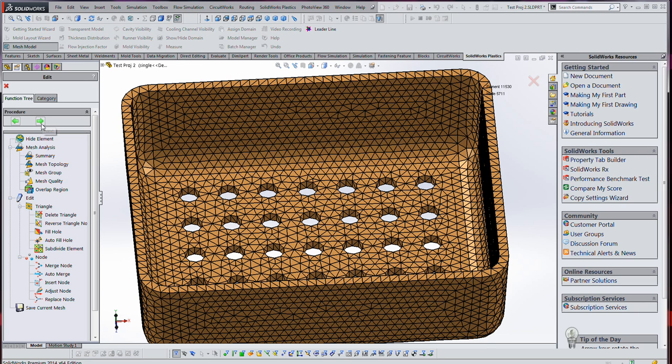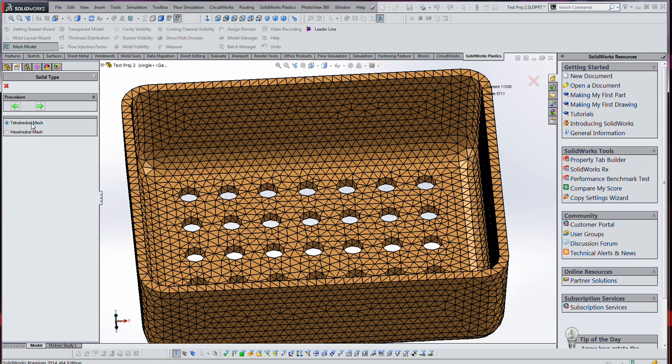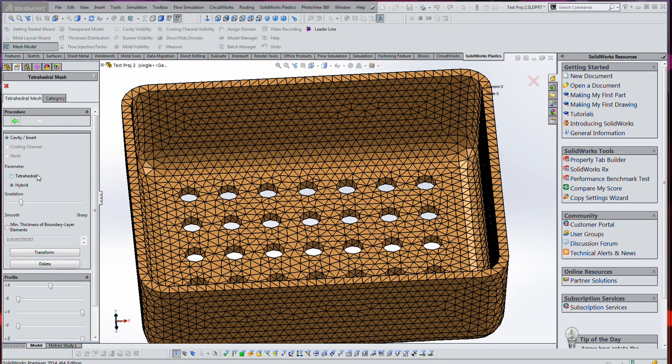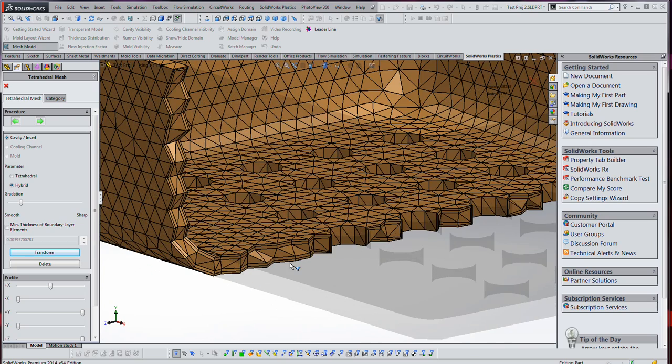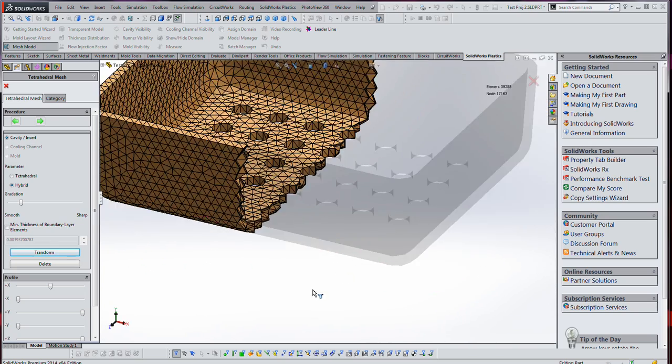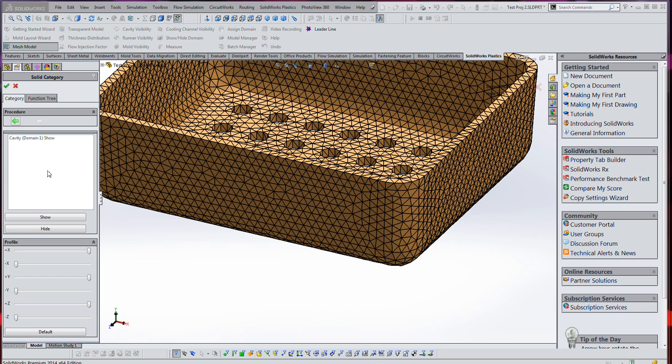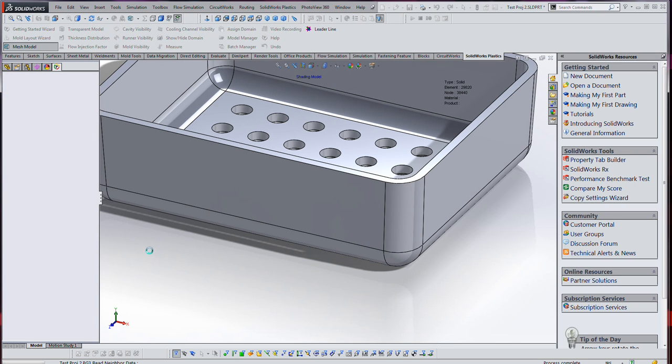So there's all this other stuff that we can deal with, but we got to define the internal mesh because we're dealing with a solid mesh type. So, I'll just leave it at default and hit transform down here, and when you do, you'll see it does a split away, which lets you look at the internal version of the mesh. Okay, so I'm going to go ahead and accept that, and then notice at this point that we got an OK. Really we can't go any more, and it kind of leads you around in circles, but that's what I did. I just kind of hit OK.